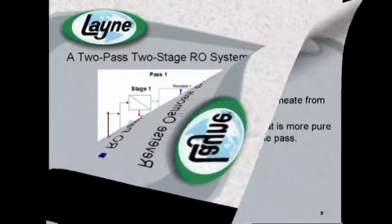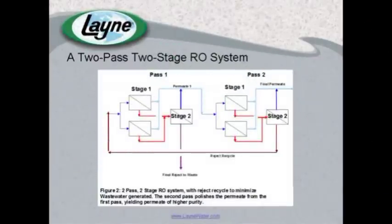So in figure 2, we can see a two-pass, two-stage RO system, a pretty common type of arrangement where you get a little bit of the best of both worlds. You reduce the amount of waste because it's a two-stage system. You increase the quality of that permeate because it's a two-pass system. In some cases, you'll want to take this out to 2 or 3 stages and/or 2 or 3 passes, depending upon your particular application.